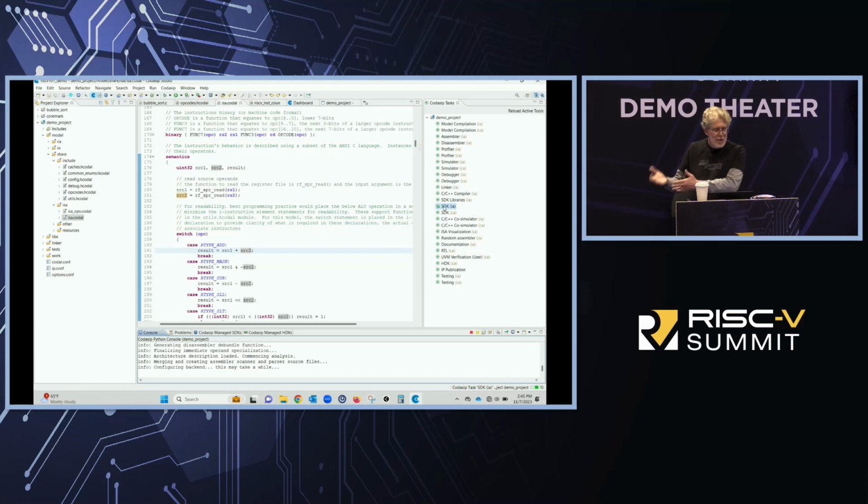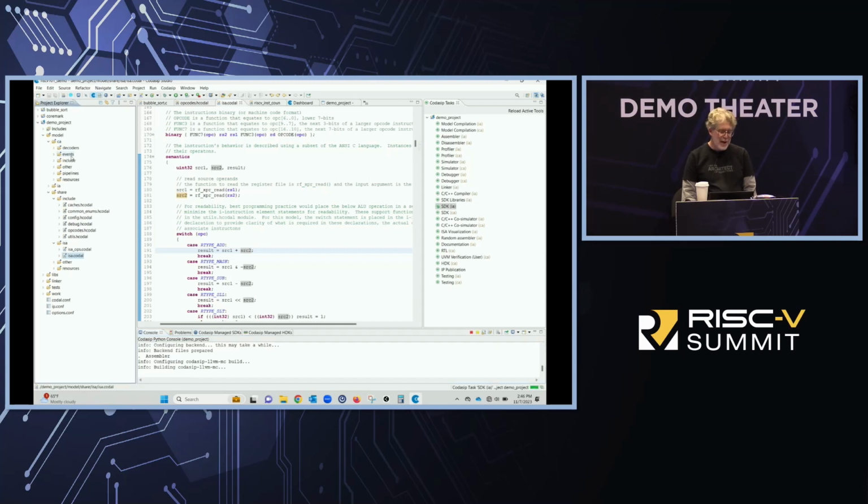As it's going to do that, I'm now going to implement that into the cycle accurate model. From the cycle accurate model, I can now generate the Verilog or SystemVerilog to generate the RTL to actually be used in synthesis. Anytime you add a cycle accurate function, there's basically 3 things that you normally have to do.